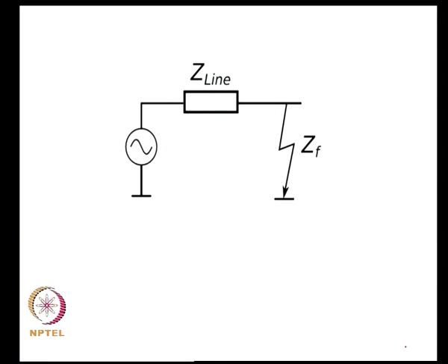So, if you look at the model for a typical line, this is what we just discussed, and if you look at what happens during a fault such as an insulation fault or some sort of short circuit fault, you can have different varieties of fault depending on your fault impedance. So, the question is, what number do you use for typical values of the fault impedance in a fault scenario. Okay. So, would it be okay to have ZF to be 1 per unit? That would not be reasonable, because it means that the current it is drawing is actually just rated current.